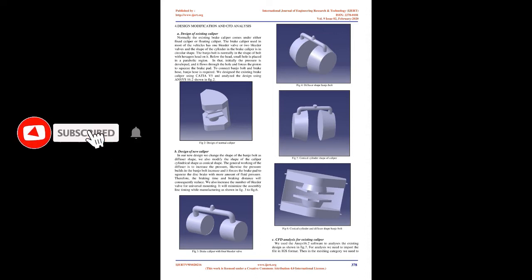But the thermal conductivity of aluminium is high, around 200 to 250 W/mK, which causes the heat generated due to the friction between rotor and friction pads to be transmitted through the piston. This leads to a decrease in disk temperature, but as the heat is transmitted to the brake fluid, it may increase the temperature of the fluid. Higher fluid temperatures may cause changes in compressibility and evaporation of the brake fluid.